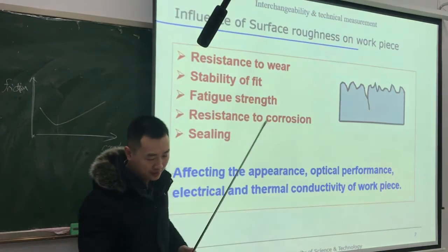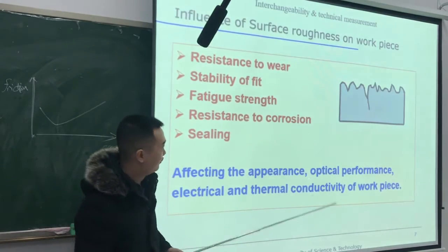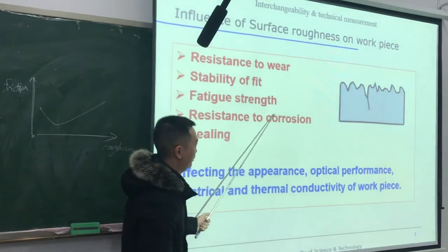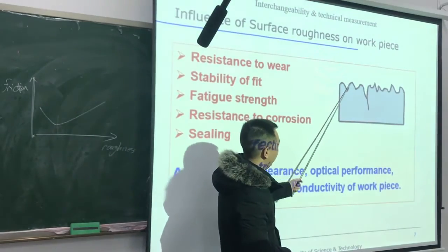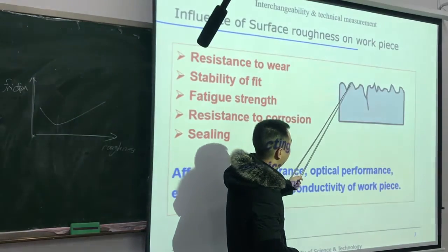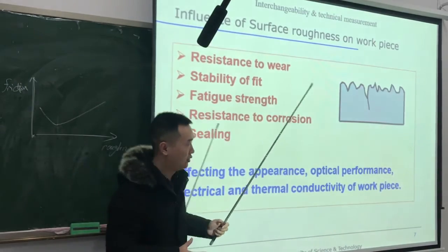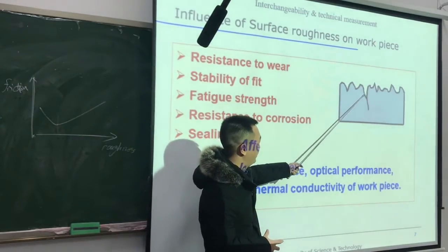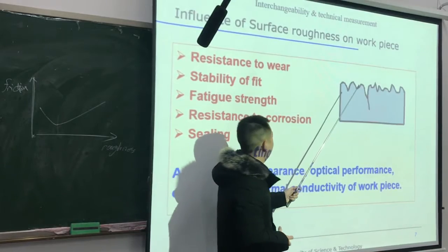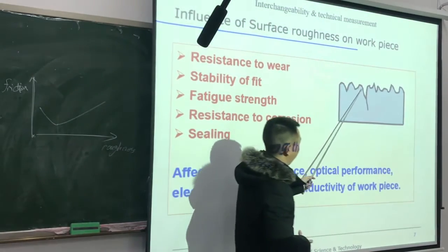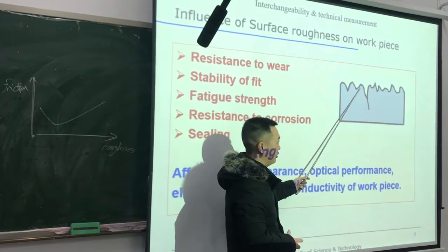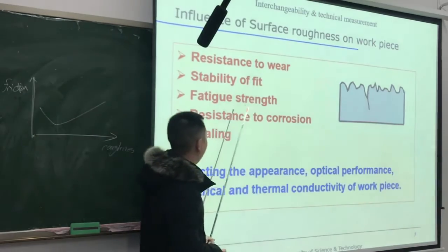And it will also affect the fatigue strength, because if there are many peaks and valleys, then it will be more easily affected by alternating force, and it will fatigue more easily.